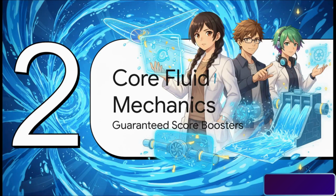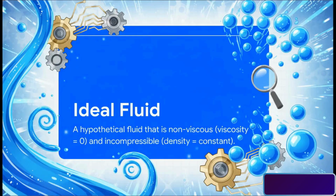Okay, first up, fluid mechanics. Now these are your score boosters. Seriously, they're the kind of foundational concepts that show up in questions you can solve pretty quickly. If you can just nail these down, you're already building a solid base for a great score. So, let's start with the idea of an ideal fluid. Now, yeah, it's a hypothetical thing, a theoretical model, but it's the starting point for so many problems. All you really need to remember are two things. It has zero viscosity and its density is constant. So, it's non-viscous and incompressible.